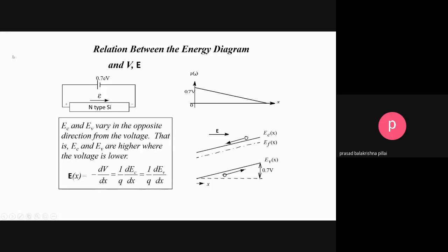For example, you can see that you have applied 0.7. Oh, this is the energy actually. 0.7 eV, electron volt, means the energy. So this is shown as energy, but we will be applying it as a voltage. If you want to find out the voltage corresponding to that, you have to divide it by the electronic charge.